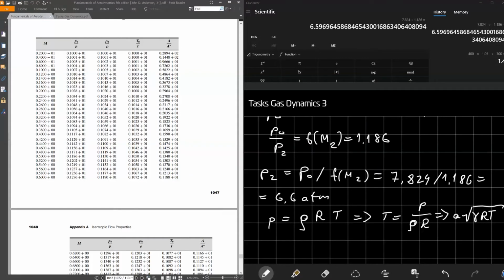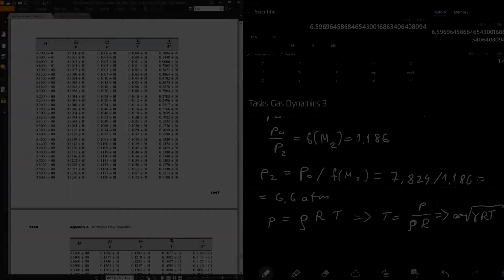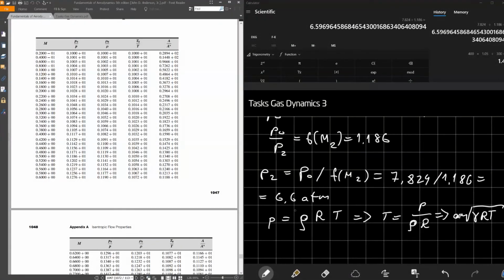And the speed of sound. Actually, I like this equation of speed of sound a lot. It's so nice, just three letters under the square root, and you receive quite an important physical property of the flow. It's a very nice thing. So don't forget that the equation of state is always available, and you can always use it, no matter what the flow is, isentropic or not, subsonic or supersonic, compressible or incompressible. Basically, it's the universal equation, allowing you to get any thermodynamic property when two other properties are known.